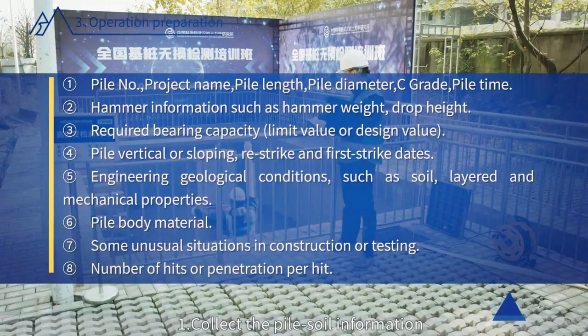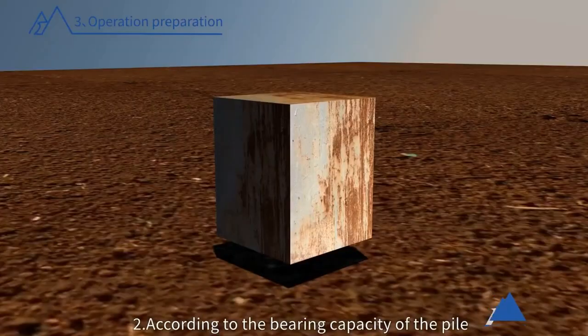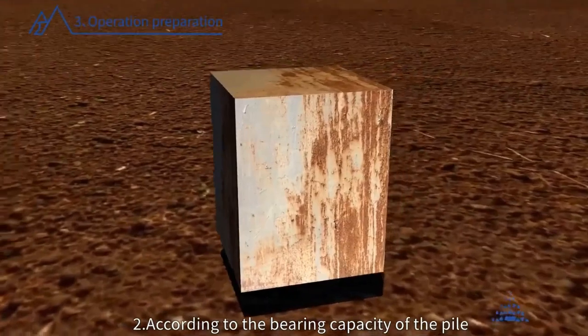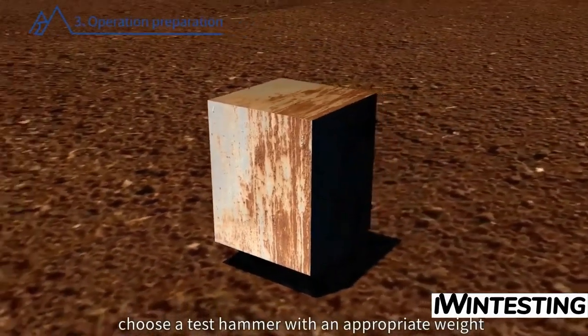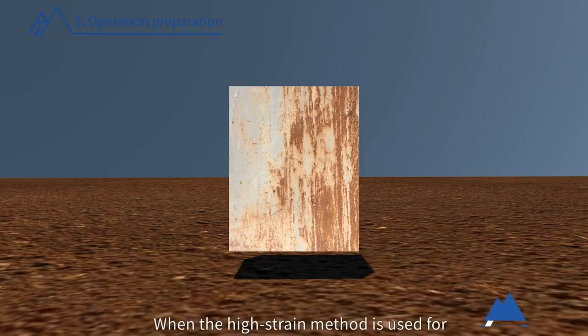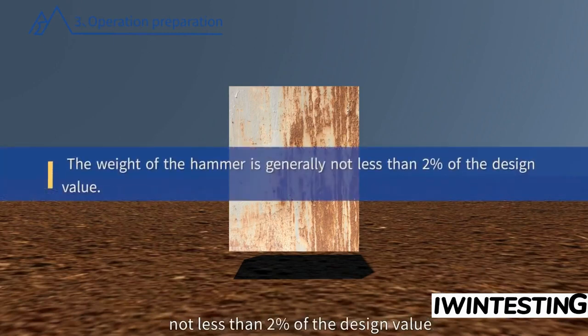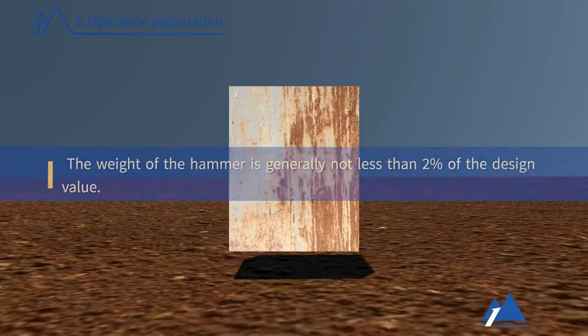1. Collect the pile soil information and geological exploration report. 2. According to the bearing capacity of the pile, choose a test hammer with an appropriate weight. Specification requirements: when the high-strain method is used for bearing capacity testing, the weight of the hammer is generally not less than 2% of the design value.